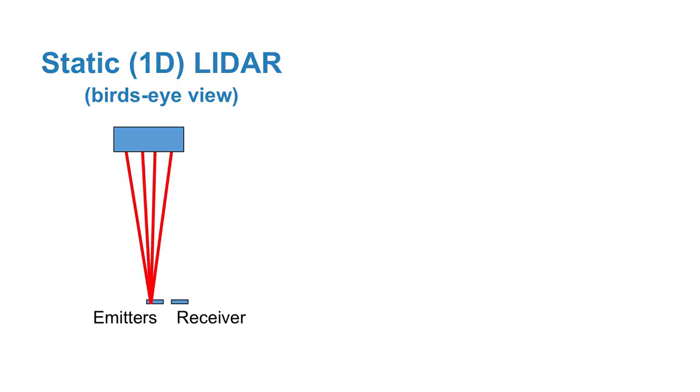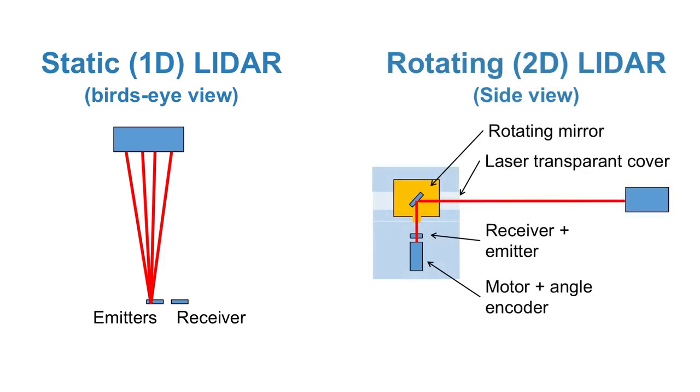There are two main types of LiDARs for automotive safety applications. The static LiDAR, which includes one or more fixed LiDAR transmitters pointing laser light beams away from the vehicle. This sensor type is relatively inexpensive, but the application areas are limited by the typically very limited angular coverage of the beams. The rotating LiDAR, on the other hand, is more expensive, but much more versatile.